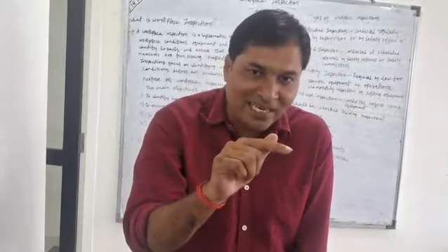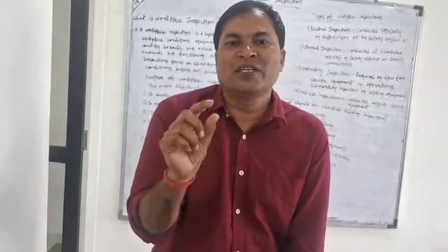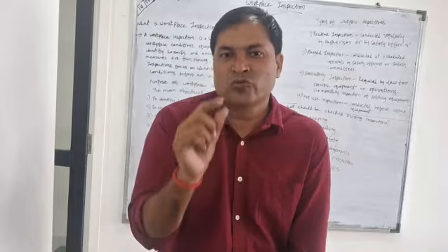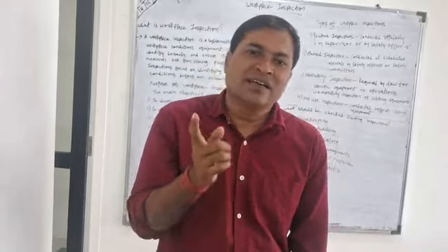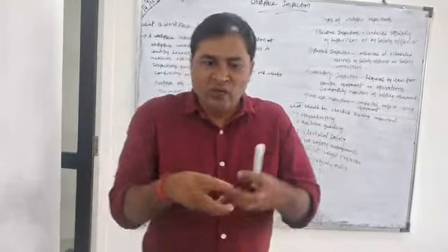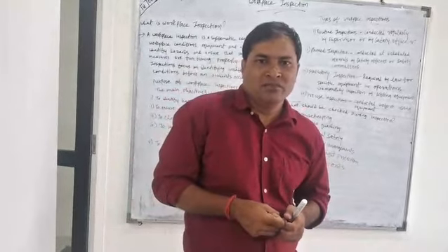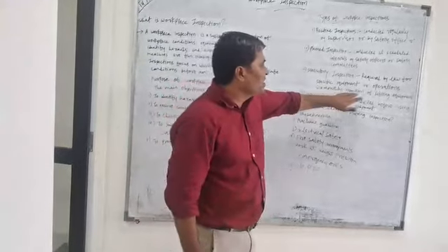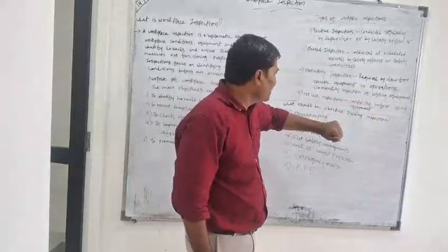You need to check each and everything related to the crane operations, equipment, lifting operations, wires, ropes, belts. Every 6 months you need to check the load lifting capacity. Understood? So that kind of thing is very important. 6 monthly inspection of the lifting equipment.